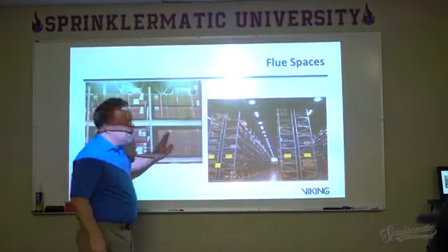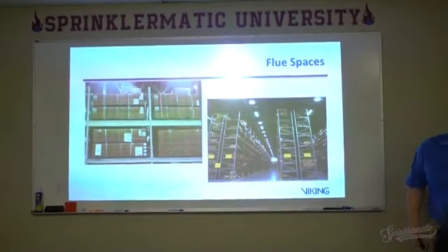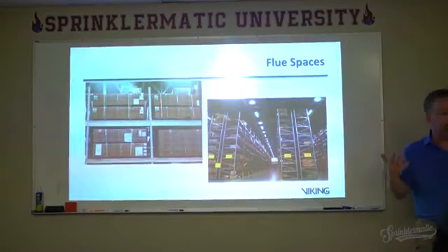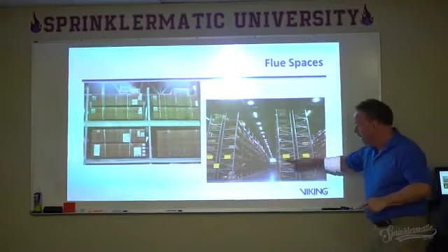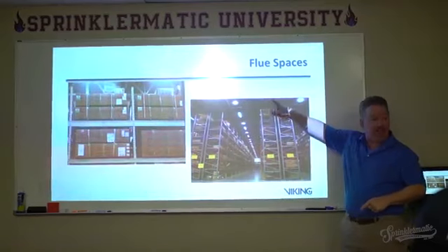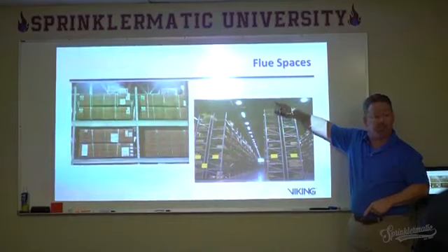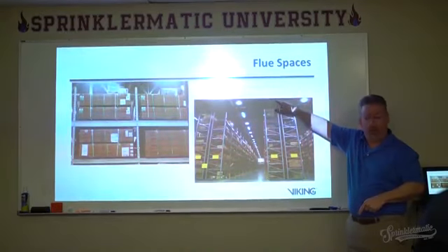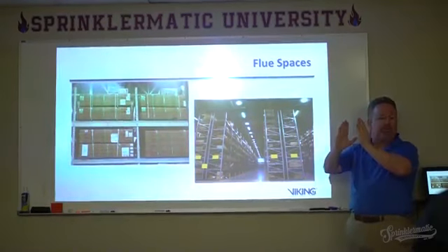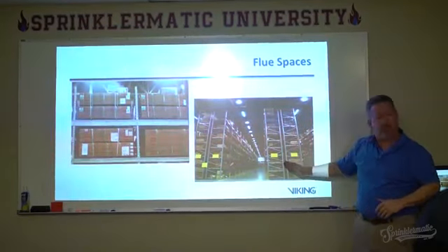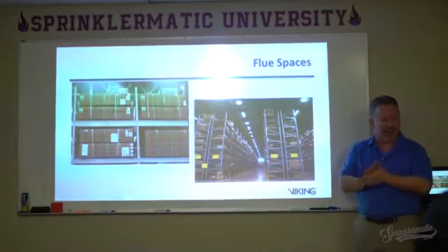And these are important. Flue spaces are important in rack storage for two reasons. Now remember, we said they entrain a lot of air in there so it gets a fire going. But what it also allows to happen is, if I get a fire going in here, it allows that heat to go up through the structure. Where are my sprinklers? They're at the ceiling, or they may be somewhere in racks here. It allows that heat plume to travel up through. What does it also allow once the sprinkler operates? Water to come back down.